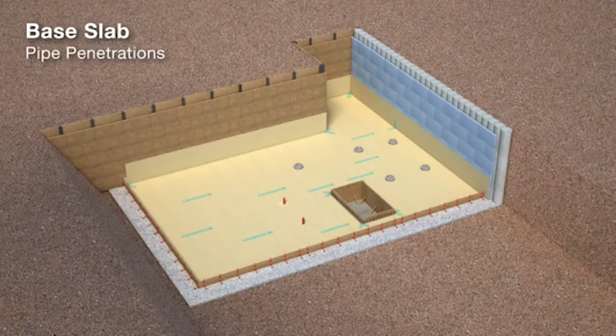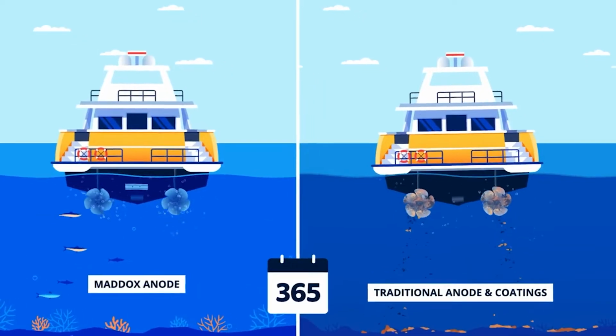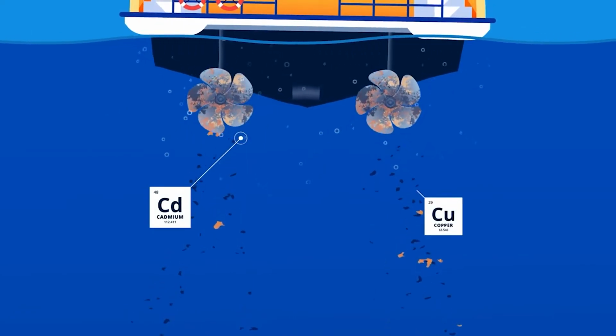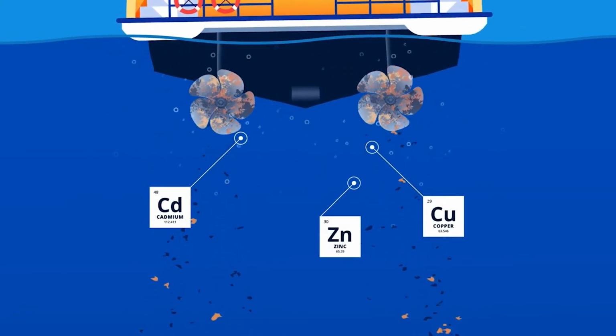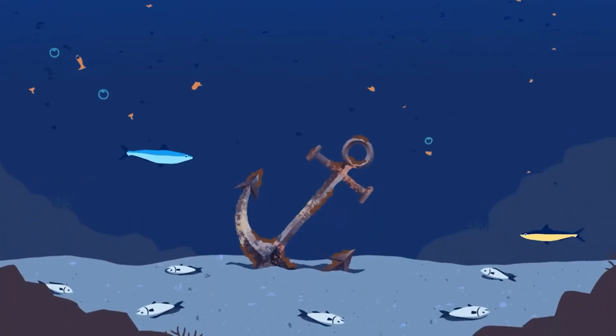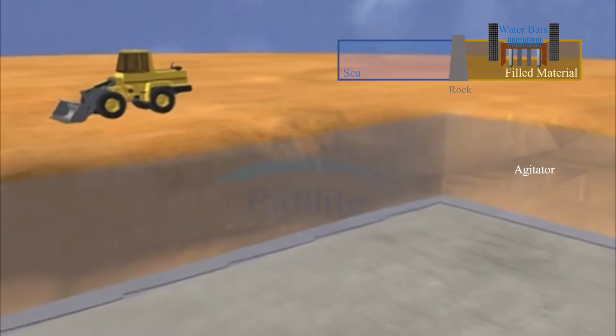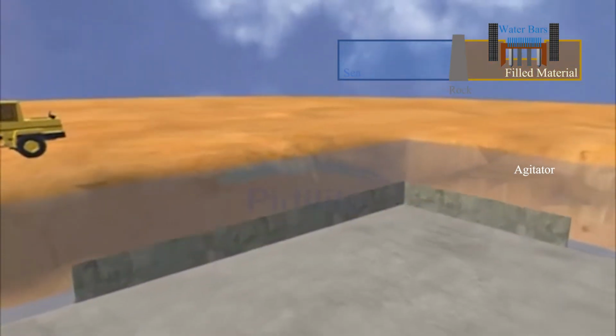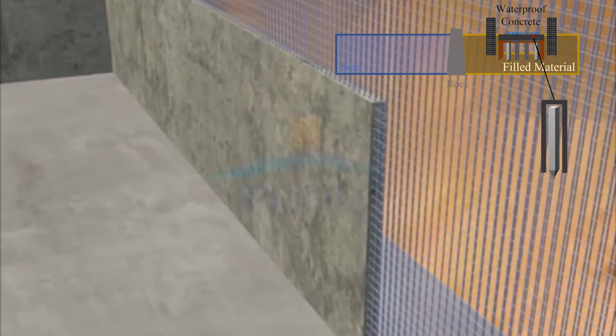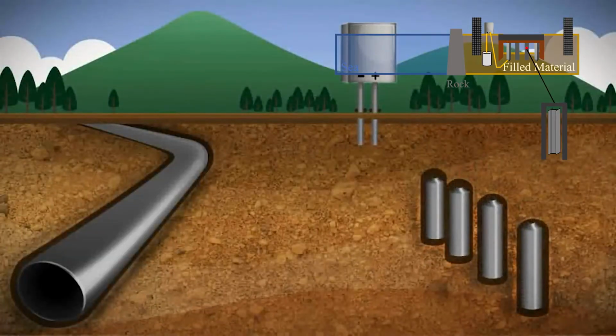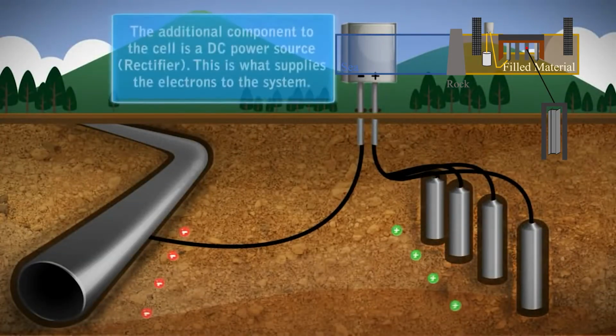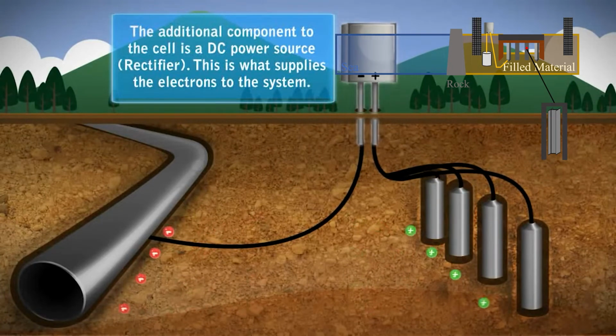After that, waterproofing work was carried out to protect the concrete foundation. Waterproofing is essential because salty water, which causes corrosion in everything, is the enemy of the museum and the precious objects they preserve. A water bar was placed on the concrete pile and waterproof concrete was poured into the upper part to form a waterproof membrane around the piles. The steel pile was coated with an anti-corrosion coating and the cathodic system was wired for corrosion management.